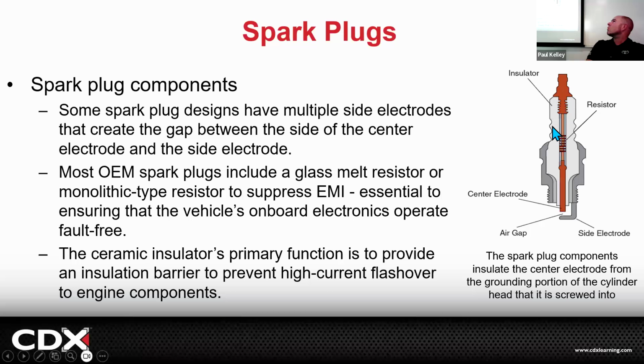But what about when we're working on this? You think it'd be fairly easy to crack that porcelain or ceramic? Well, what if you don't use a spark plug socket and your metal socket hits that? Oh, you'll bust it. Yeah. Or if you drop it from a height, you'll break it, so these are not real durable. You got to be careful.